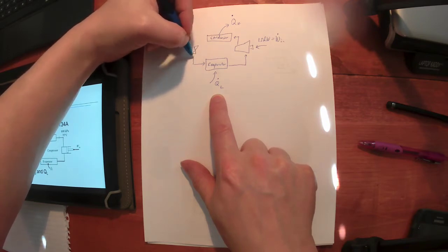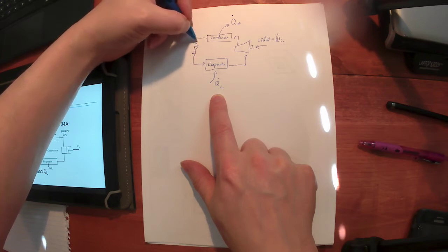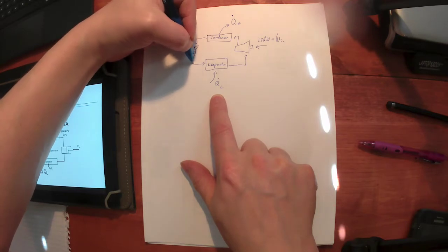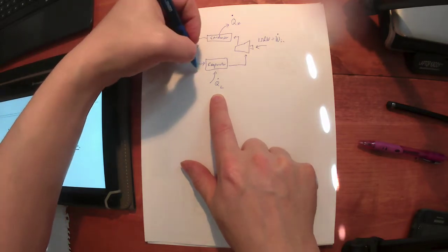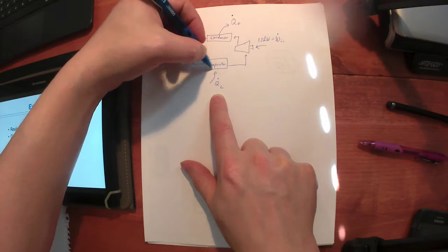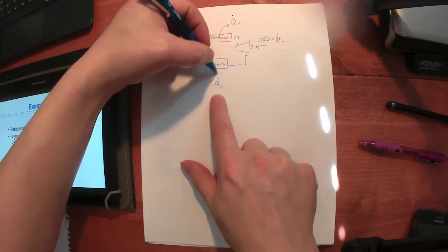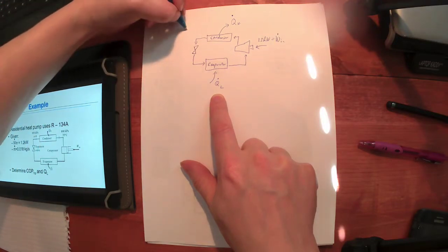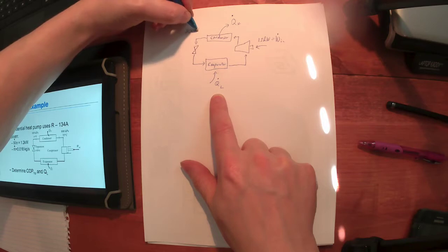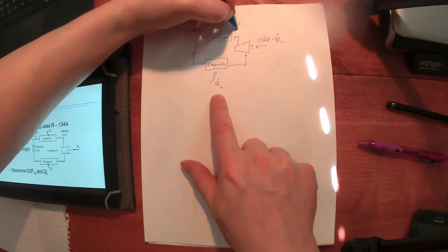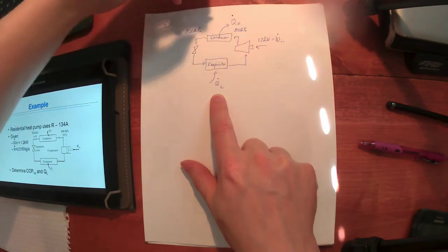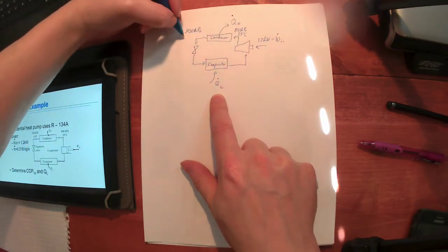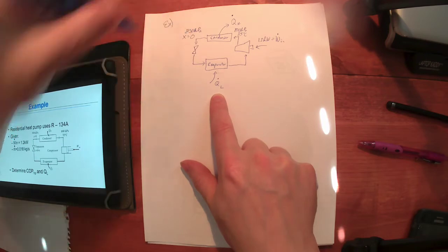We talked briefly about this in the last period. The idea is if I've got a high pressure fluid, I allow it to expand and go to a lower pressure, the temperature will drop, and the goal is to get the temperature to drop so far that the refrigerant at this point in the cycle is so cold it will absorb heat from the lower temperature, colder source. Now they've told me that I've got 800 kilopascals, fairly constant throughout the condenser. They've told me that it's coming in at 35 degrees C and it's going out as a saturated liquid.